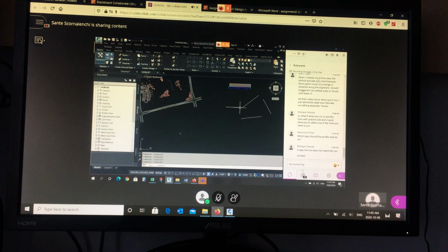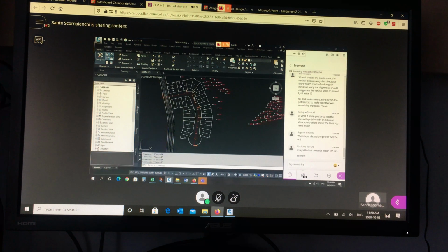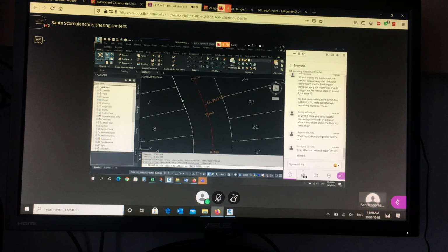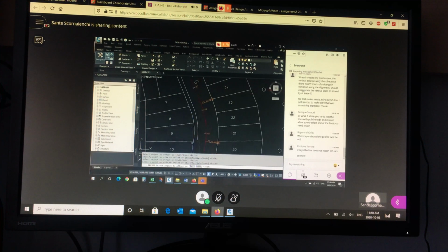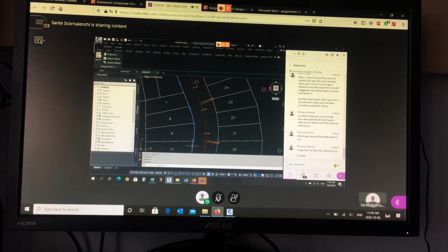When you're designing the road, right in here, you should use a fillet command. So it should be connected at either end. Here, when you offset, I'm just going to use 3 as an example, just so it's a different spot. If I offset 3 meters, and then I offset 3 meters, and I offset 3 meters, when I go to polyline edit, and I join this to this to this, if it doesn't connect, which in my case it does, then maybe somebody drew this incorrectly. Because if these didn't have the same coordinate, then the offset won't have the same coordinate. If they're not tangent, it won't work.